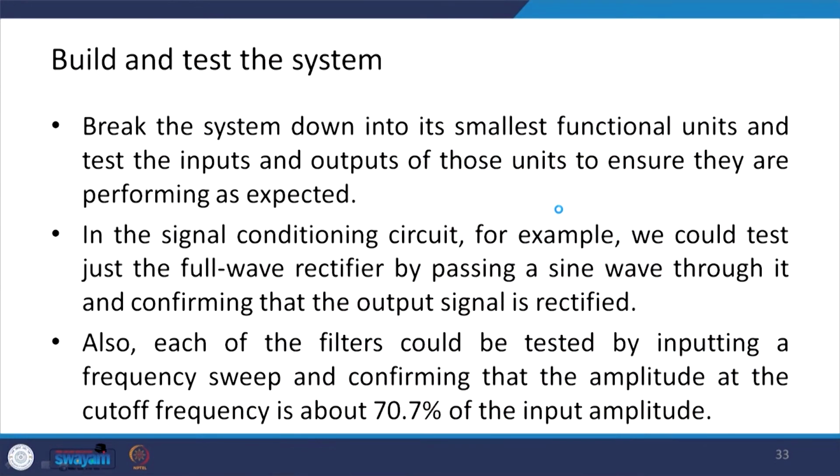Okay. So, break the system down into smallest functional units and test the input and output of those units to ensure they are performing as expected. The signal conditioning circuit, for example, we could test just the full wave rectifier by passing a sine wave through it and confirming that the output signal is getting rectified. Also, each of the filters could be tested by inputting a frequency sweep and confirming that the amplitude at the cutoff frequency is about 70.7% of the input amplitude.